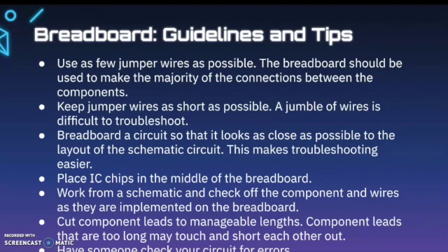Also, you want to make sure that you're laying out your circuit in a way that it looks as close as possible to the layout of the schematic, so that way you can follow along and make troubleshooting easier if something isn't working correctly. Also, IC chips should always go in the middle of the breadboard. We haven't talked about IC chips yet, but when we get there, I'll make sure I demonstrate that for you.